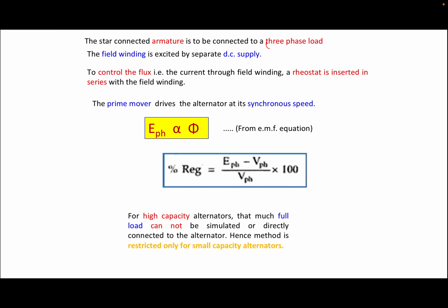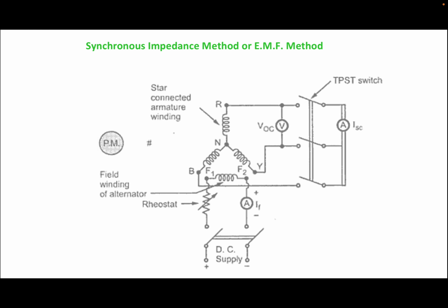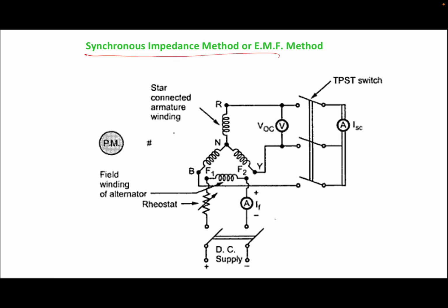For high capacity alternators, full load cannot be simulated directly here. This direct loading test is suitable only for small rating machines. So let's discuss the first method here, the synchronous impedance method.